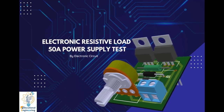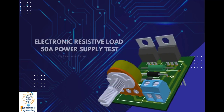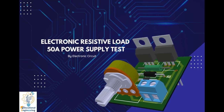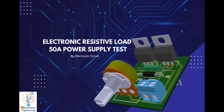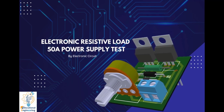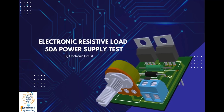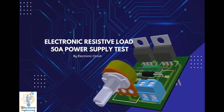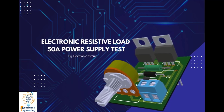Hi, and welcome again to another video. Today we're going to learn how to design an electronic resistive load, 50 amp, originally made by Electronic Circuits. This board is capable of withstanding an initial load for low voltage sources: 4 volts at 40 amps, and for voltages above 5 volts, the current is 50 amps, supporting voltages up to 45 volts. So let's start designing it in Altium Designer.